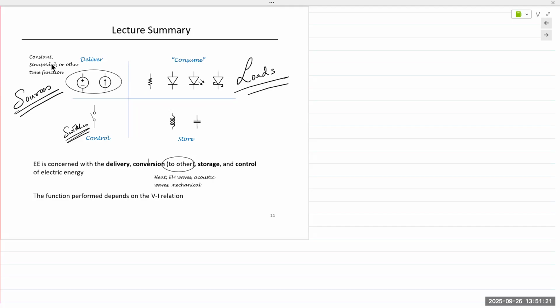Inductors and capacitors can behave like a source if they do have stored energy. But they cannot supply this energy infinitely. There is a finite end to that supply. So a capacitor or an inductor can store energy and can supply energy, but that supply is not infinite. It stores energy and then releases it back into the circuit. The time difference between storing and releasing could be as small as nanoseconds, microseconds, milliseconds, depending on the size.